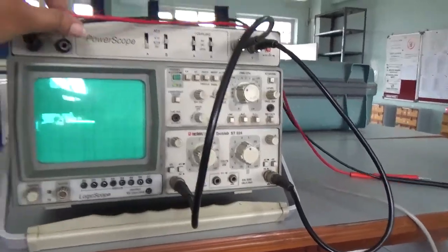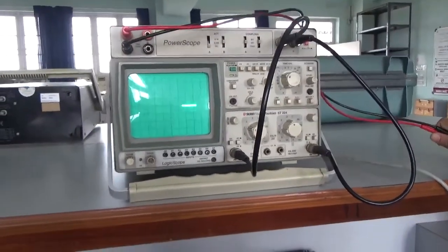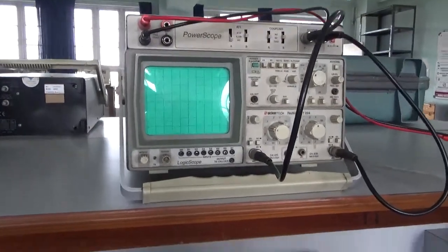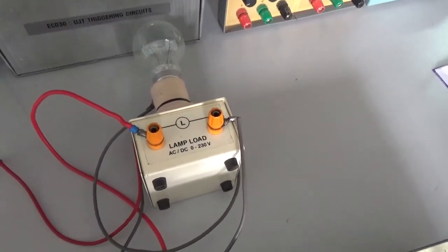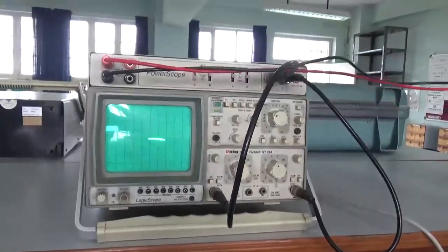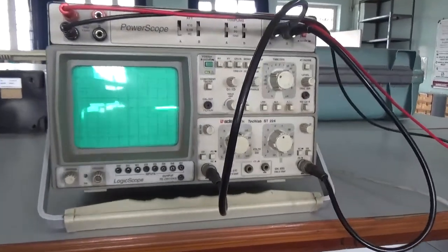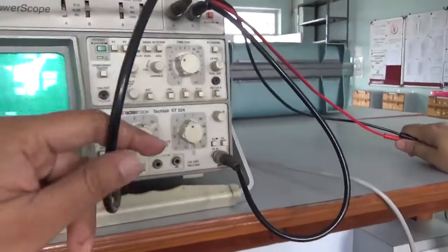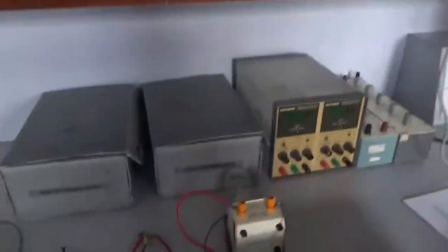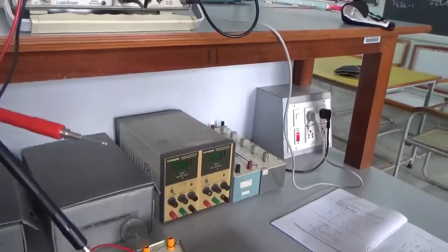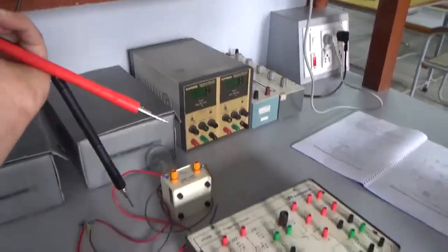It is very important to measure waveforms using this oscilloscope whenever you are measuring the 230 volts supply, or the voltage across the load. This is the bulb load we have in the lab. If you are measuring voltage across this load also, you are supposed to use this power scope. The usage of this power scope is the same as a normal oscilloscope. The only difference is, instead of taking the probe from here, you take it from these two terminals, with connections like those of a multimeter. Using these two probes, we can connect wherever we want and measure the waveform.